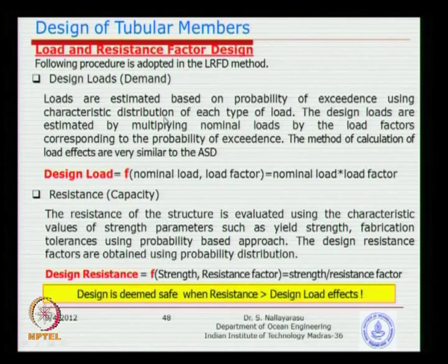For example, take an environmental loading. Wave heights at a particular location could be 10 meters, at another location 20 meters, but not going to be 200 meters. So if you look at a probability distribution of wave heights, you could see a pattern that you can arrive at. If you look for 99% non-exceedance, maybe you will get 15 or 16 meters. If I want 100% non-exceedance, then I take 20 meters and design for it. If I want to take a 90% probability, then I can design for lesser values. That is where the estimation of load becomes more scientific.